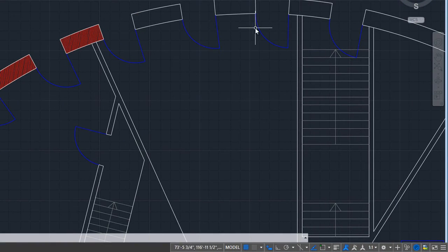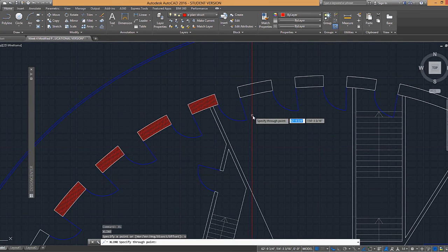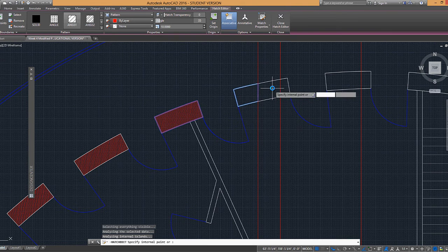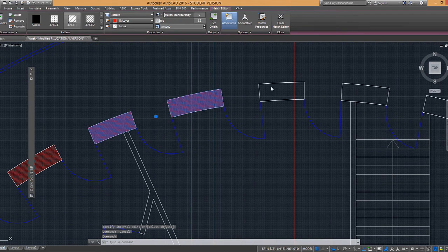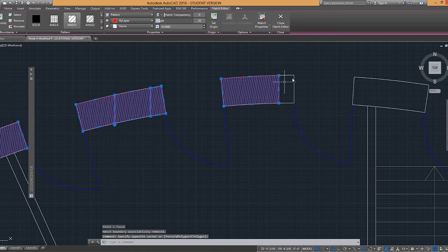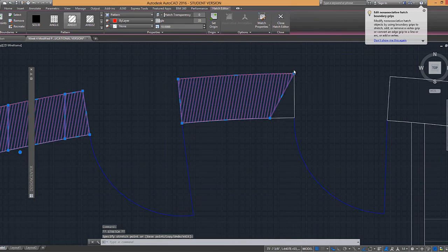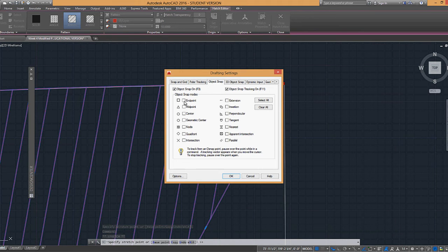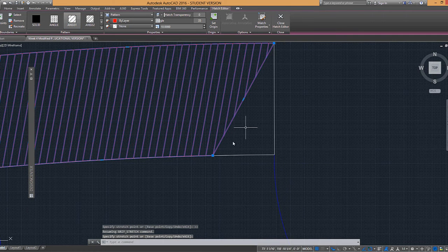I'll also break it up into smaller pieces, either with my construction lines, because I find that AutoCAD tends to work best with hatches in well-defined small bites. So I can take this and add to it like that, using construction lines as boundary lines. If I ever want to change the hatch, in newer releases it's associated with grips so that I can stretch it. I'm turning my object snaps on, and I can stretch it to certain points on my object.